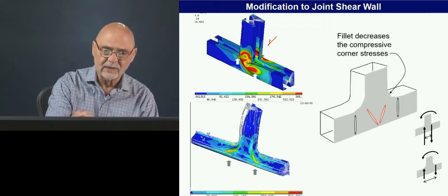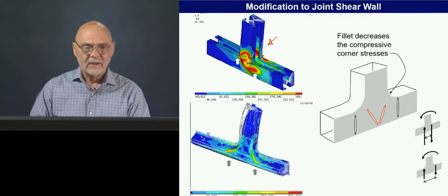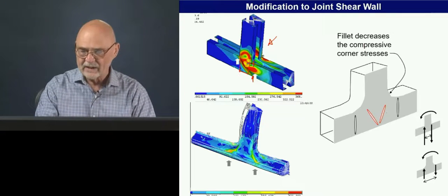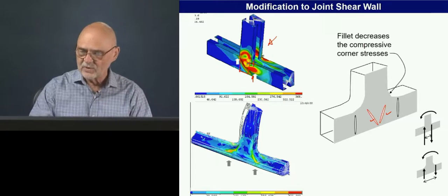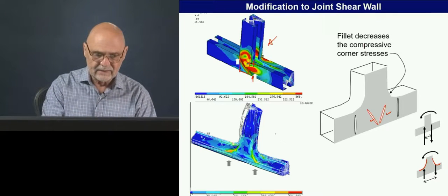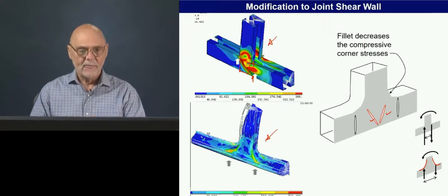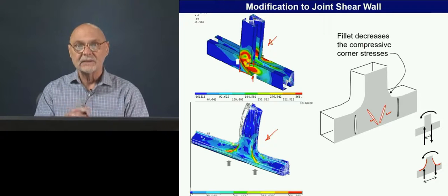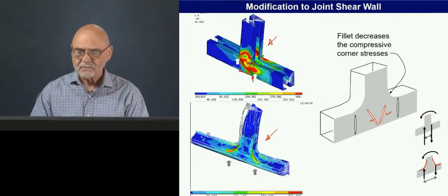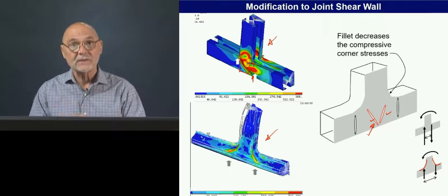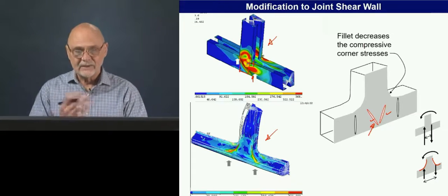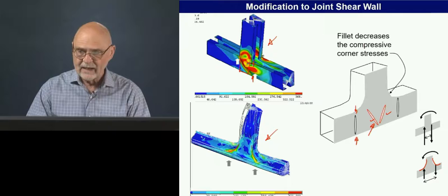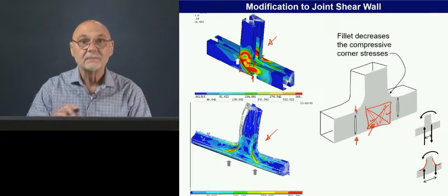Here was the untreated case. We had buckling occurring here and buckling occurring here. We've added our beads, we've increased the radius here, and now we get a case that looks more like a normal section, where we have much less deformation occurring at the joint itself. Okay. So these beads are the most mass efficient way to do this. There are other ways to do that, and remember we're trying to provide a load path here, and we're trying to prevent buckling here. Okay.